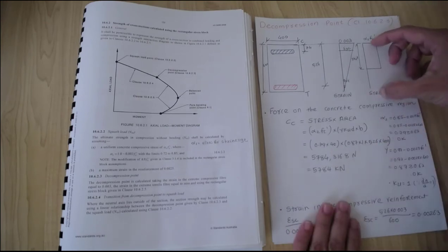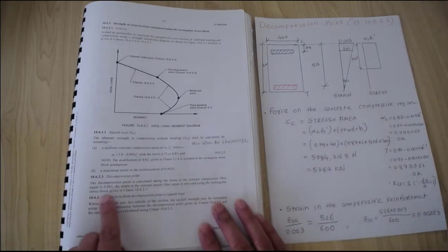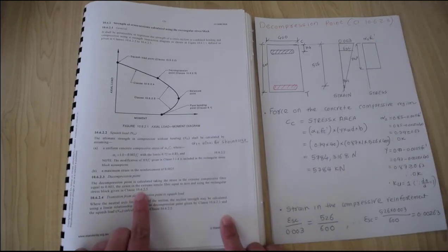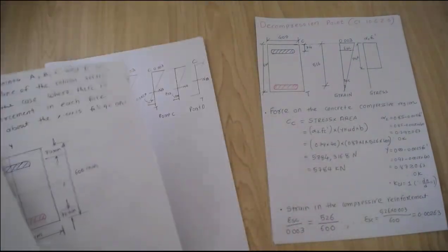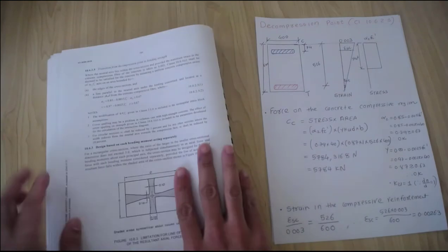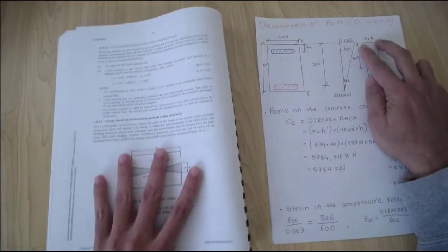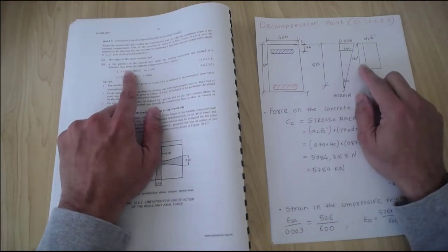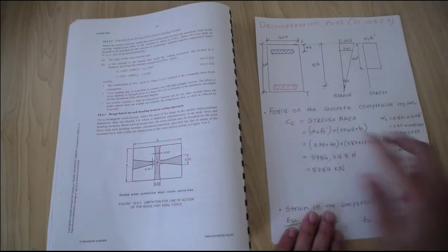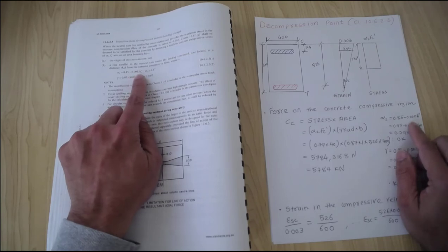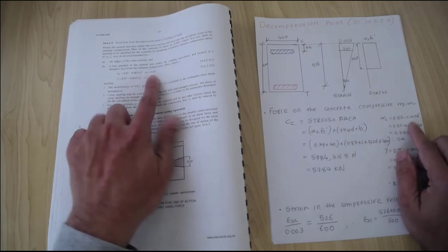Now if I draw the stress diagram, because it says that the rectangular stress block should be used to calculate the concrete forces, that is given in clause 10.6.2.5. So if I turn the page over, I would have this stress block. It's similar to the stress block we used in the beam examples, where you have alpha 2 f'c, which is the stress in the concrete, and the height of the stress block, which is given as gamma k_u d. We can calculate alpha 2 first. Alpha 2 equals 0.85 take away 0.015 f'c, and that should be greater than 0.67.